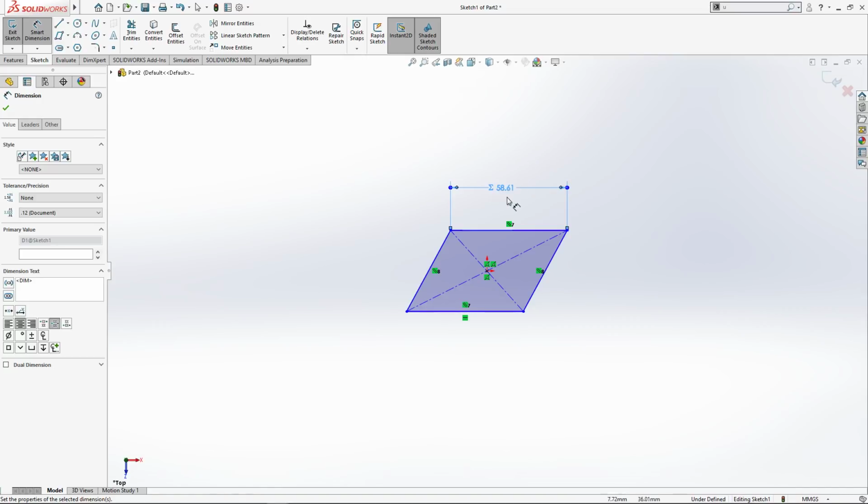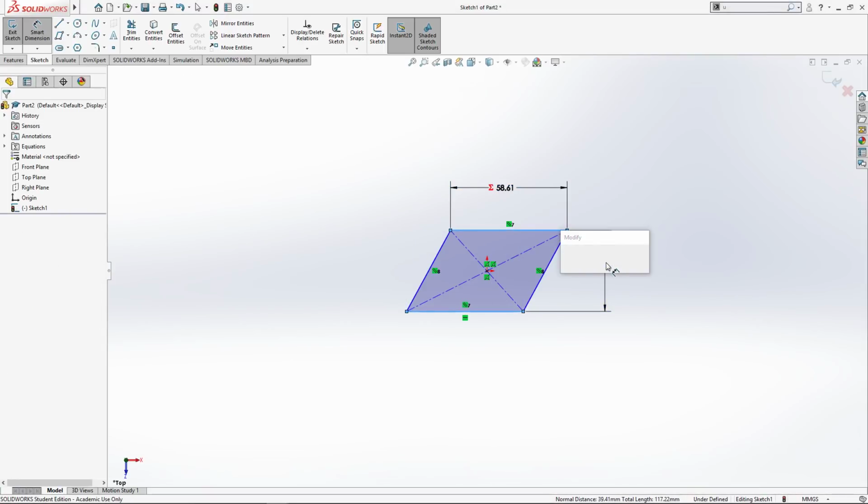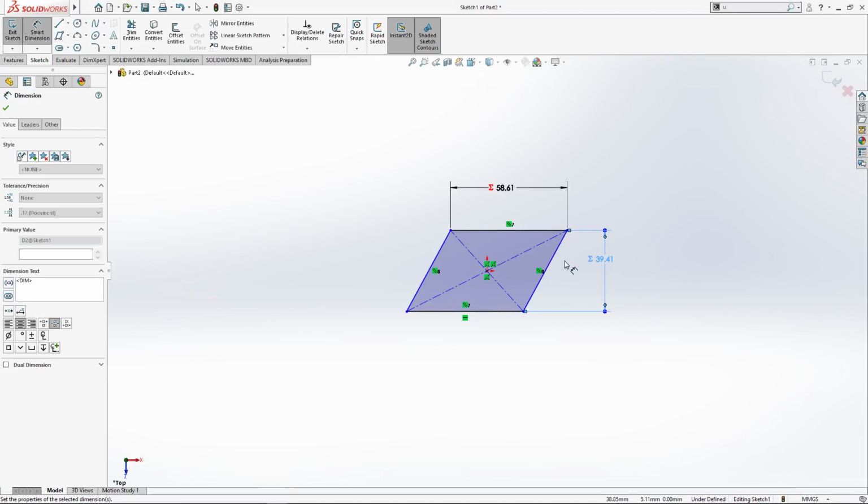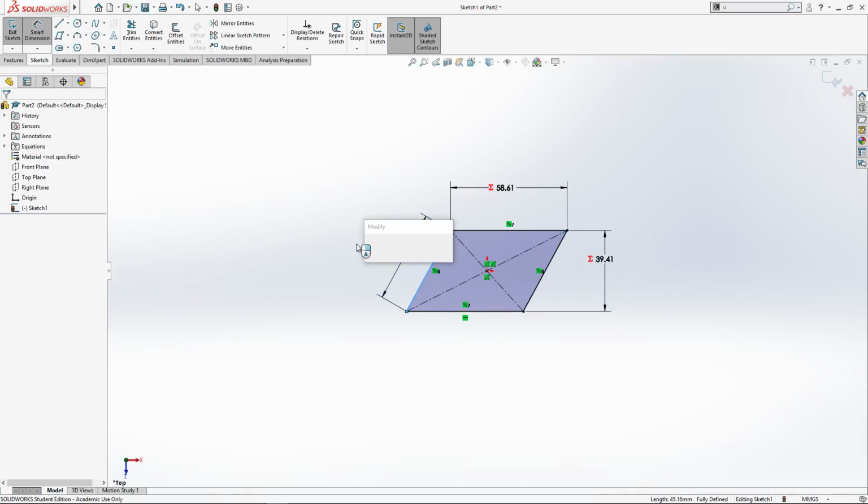And again, we don't care about the dimension right now. We're just going to go ahead and dimension this thing through. So again, this is going to be B right here. So I'm going to do equal B. And one thing that's going to happen on your computer is when you click the check mark, it's going to say, are you sure you want to create a global variable? I clicked yes, and then I said, don't show me this dialog anymore because we're going to be doing it a lot. So we can see that these are global variables.